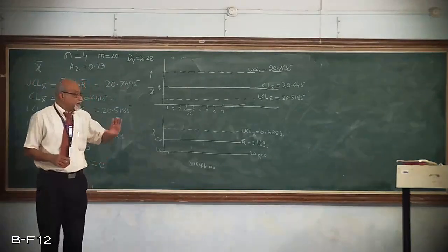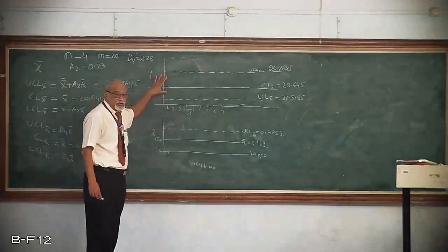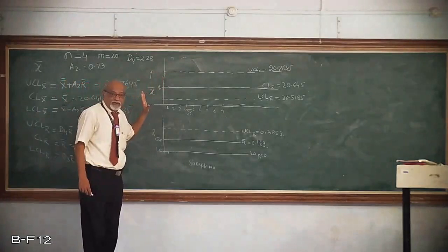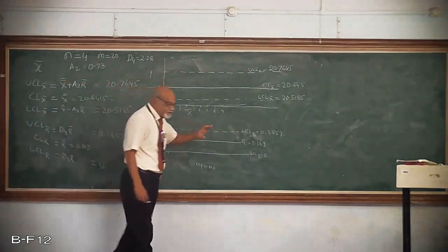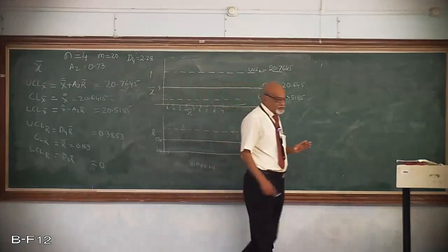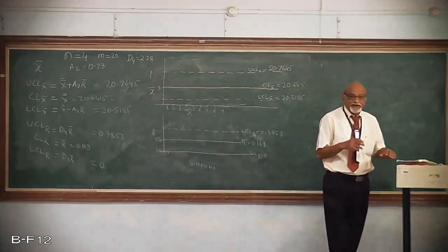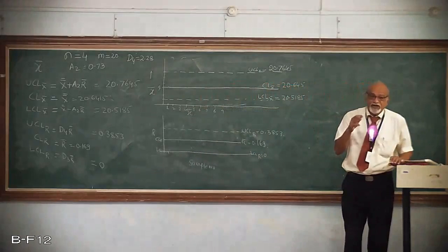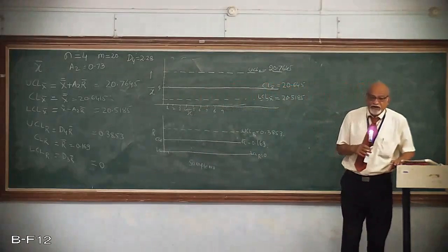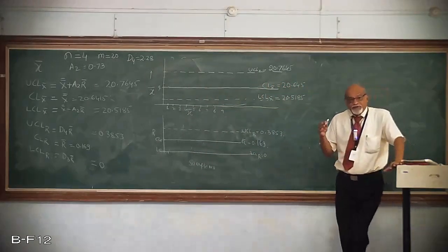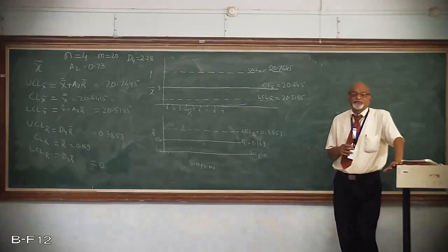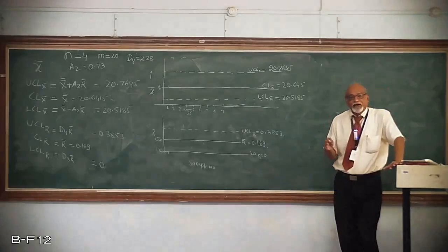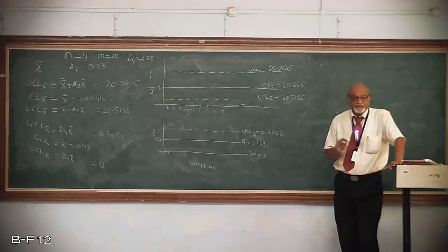If it is not falling within the control limits on the X bar chart, what does that mean? Its process average has shifted. It is no longer within that variation, that process average, whatever we expected it to vary. It has changed. That is why the process needs to be stopped and investigations are to be made.